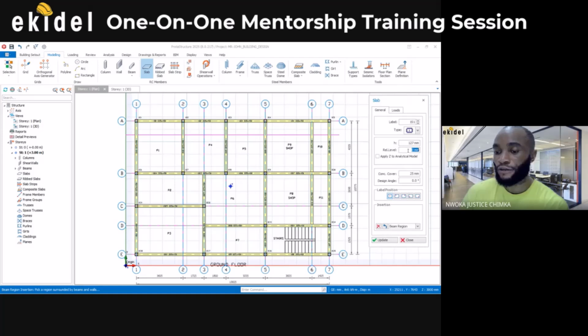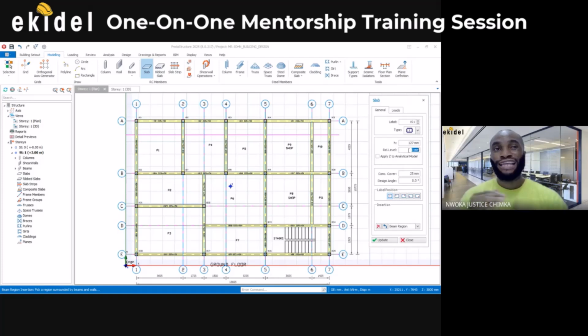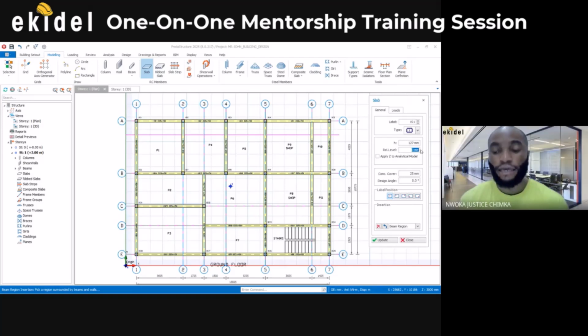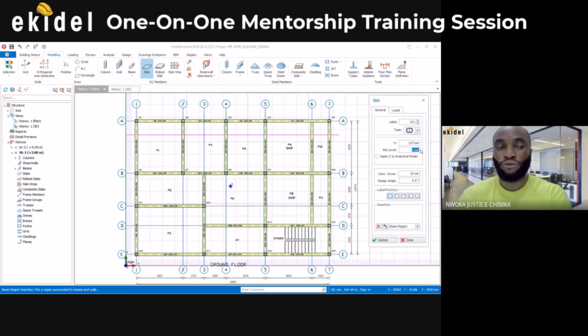This relative level is for if you have a different slab level, for example an auditorium hall or stadium that has different levels of slab for seats. What if you have a veranda with maybe a 50 millimeter step down? Exactly, you can use this to show that this one is going down by maybe 100 or 50 millimeters, and put the value here.